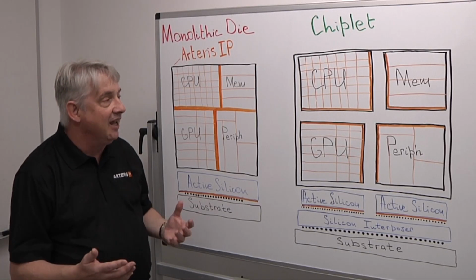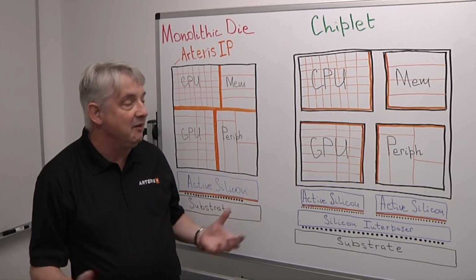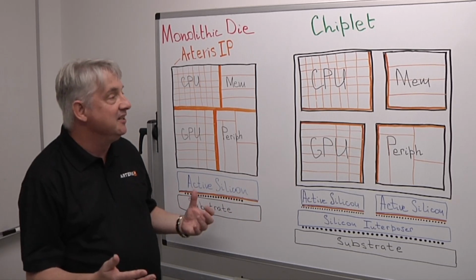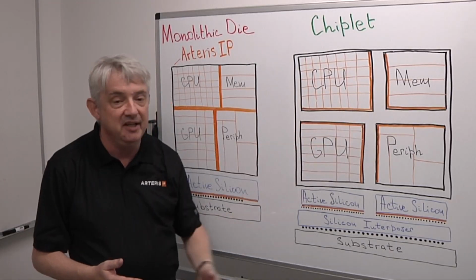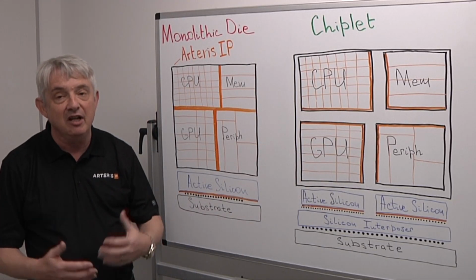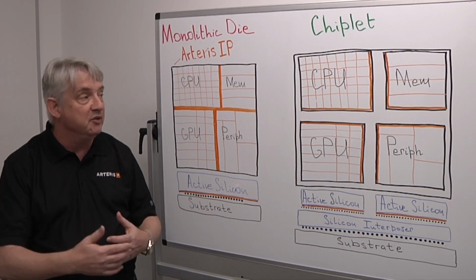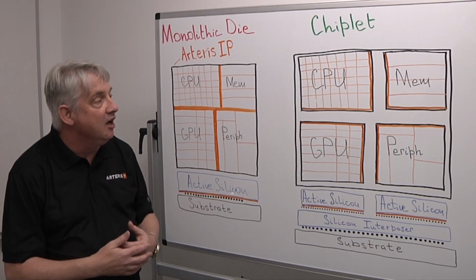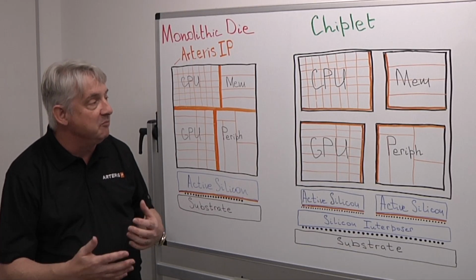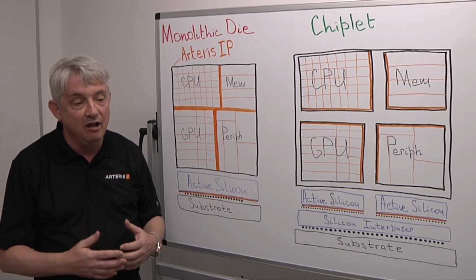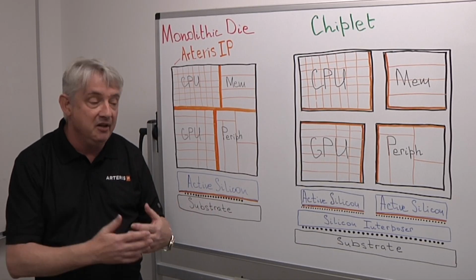The issues that you have are the usual two, if you like, which is latency and bandwidth. So you have increased latency of talking across an interface, and also you have a bandwidth limitation in terms of how much bandwidth you can get between devices. Of course, for example, there are standards like UCIe, which is becoming popular in the industry. You can gang them up.